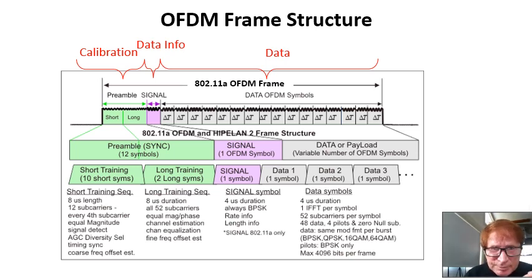Also, this transmission of pre-known values enables calibration of the receiver's sampling clock, which may differ from the transmitter's sampling clock. The transmitter also sends a single symbol after the preamble to inform the receiver of the waveform properties. For example, the specific QAM constellation.